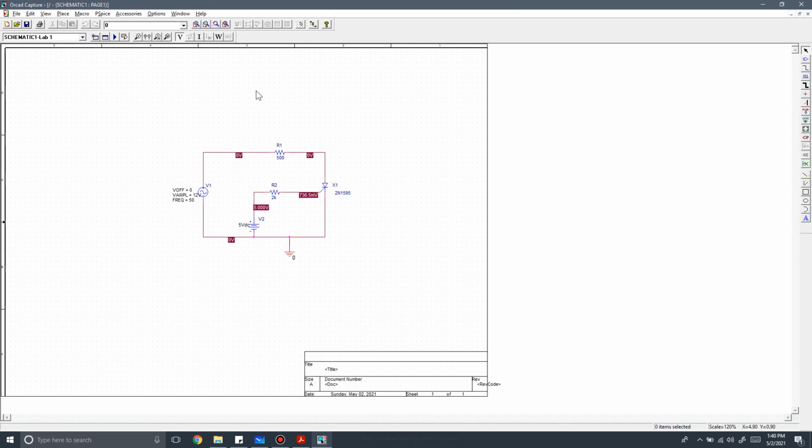One thing I forgot to mention before running the circuit: PSpice actually lets you analyze the voltage at any point. It can allow you to analyze the voltage at the anode terminal of your SCR, for example. But we also need the current. We want to observe the IV characteristics, so we also want a measure of the current in the circuit. To do that, we have to use a current probe.